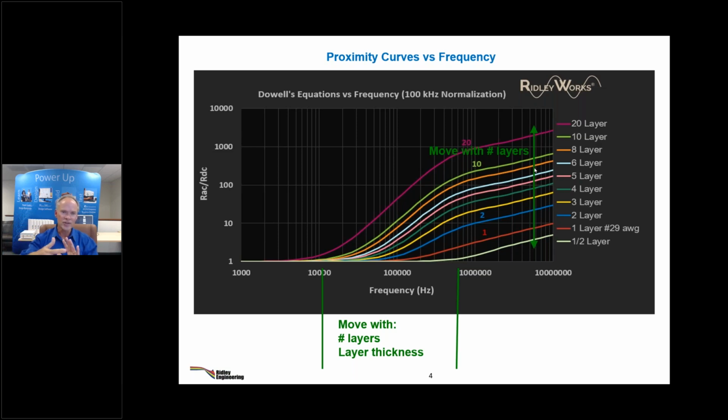Once you get above a couple of megahertz, you start seeing a curve going up because you're not sensing it properly anymore. One of the features that we have, which we haven't handed out yet, is that if you can read in 50 values with the analyzer, you just click a button, it dumps into our software, and boom, it spits out the model for you. The old HP used to do curve fitting on LC filters and things; we can give you the values if you can give us a good measurement.